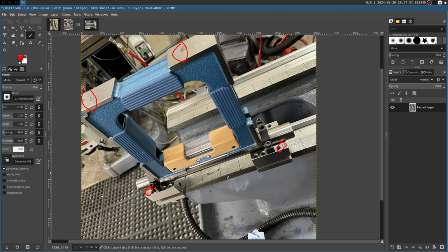If the two agree, if my mental model of how the straight edge feels and how this produces results agree, then I'm very confident in both of them. But I think I trust the level measurements the most because they are extremely repeatable, extremely consistent, and there is very little human involvement in taking these measurements.